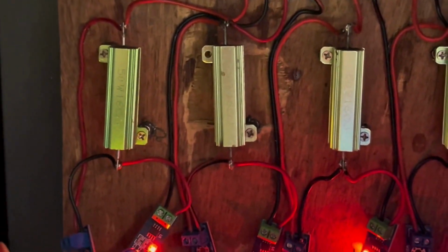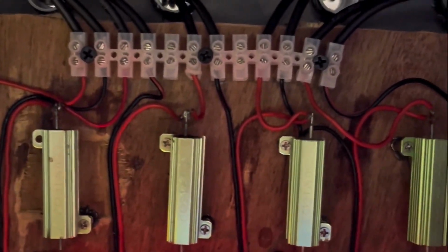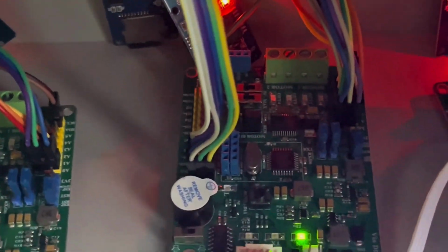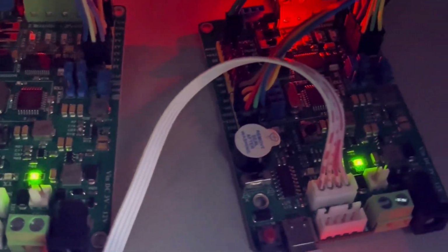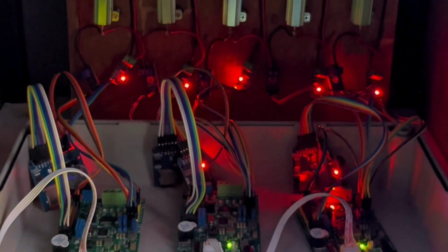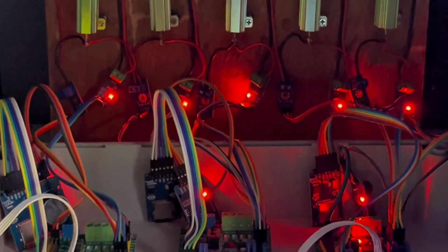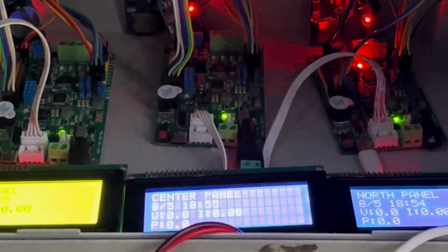Now we have our load resistor that we connect with a current sensor and voltage sensor to get the output. Now we have the SD card module, RTC, and our microcontroller, which is the Arduino Uno, for our data logger. So this is the full system, which is a data logger system to measure the output from the panel. The LCD will present the values to monitor the data.